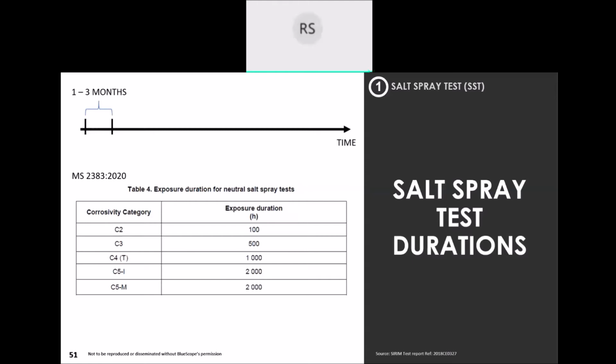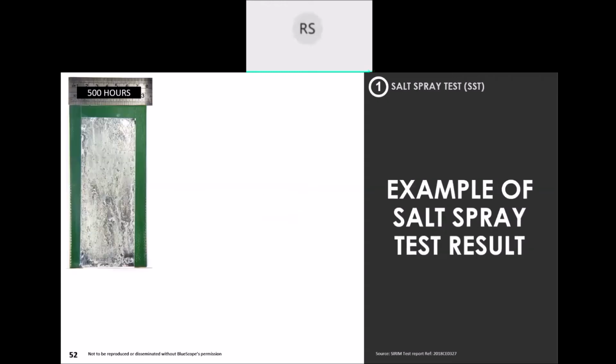But have you asked yourself, how long can it last, right? What does this 1,000 hours mean? Okay, so that is an important question. It can withstand such an environment, but for how long? In actual fact, even us who study those standards, we are not able to tell you, and we do not dare to tell you, because there's no standard method to actually estimate that. All right, so end of story for the salt spray test. The results, also called the duration of the test, have nothing to do with how it performs in actual weather, right?